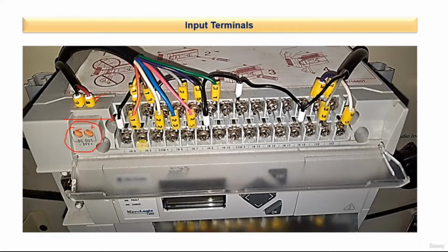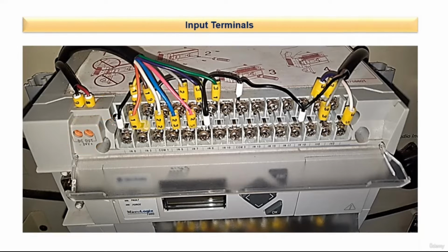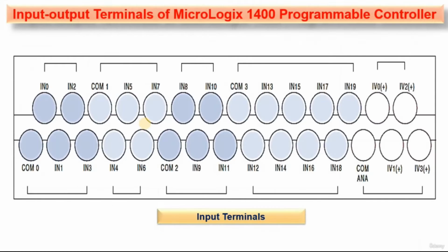So here, if you want to know the connection part in detail, here I have added the connection diagram of the input terminals. So I0/0 means what? The first input terminal. This one is the second and third, and here the fourth number, and here you can observe the common terminal, right? Common 1, this one is the common 0.